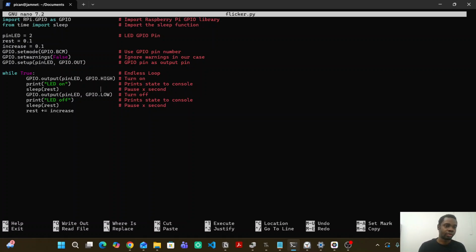Then I rest for 0.1 second. Then I go low, turn the pin off, that's pin 2 off. Then I rest for 0.1 second. So I go high for 0.1 second, then low for 0.1 second, for one cycle.